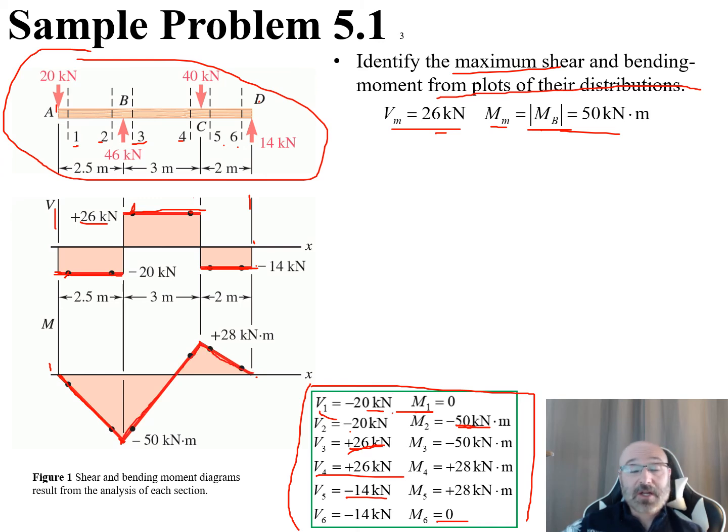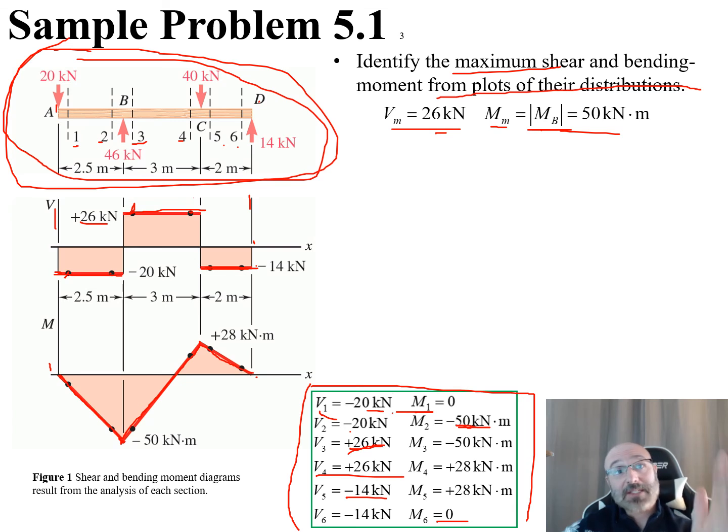like this right here. So now I have my shear and my bending moment diagrams that correspond and line up with my initial diagram up here, my free body diagram from above, at each of those points, A, B, C, and D, and I use all 6 of these sections to get the values to draw in those lines that go from A, B, C, and D.